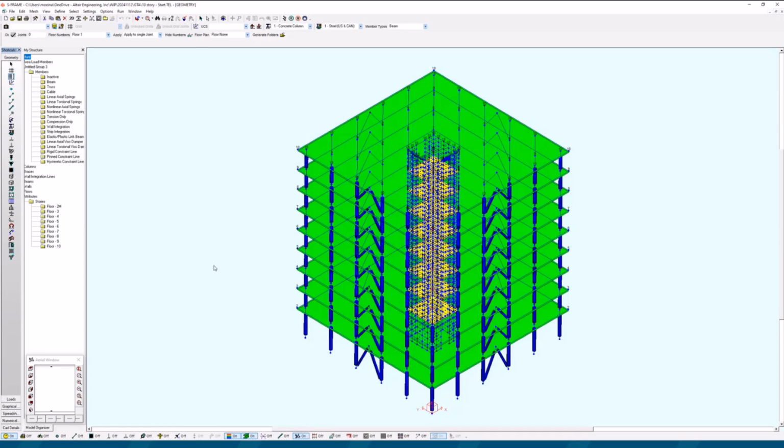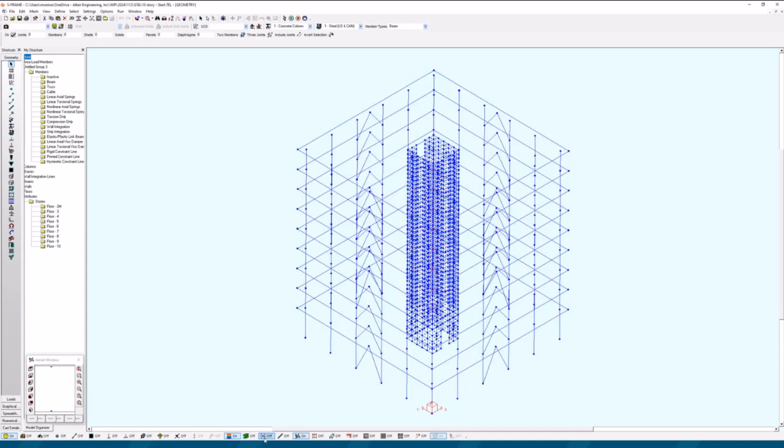But of course, if you're doing this manually, you need to be aware that there should be no gaps in the floor numbers. The other important aspect in this is having rigid diaphragms defined properly in your model. I can show how rigid diaphragms are modeled here. Each floor has a rigid diaphragm shown in pink, and each rigid diaphragm has a lead node assigned to it at the center of the geometry. This is important when applying the wind loads in your structure.